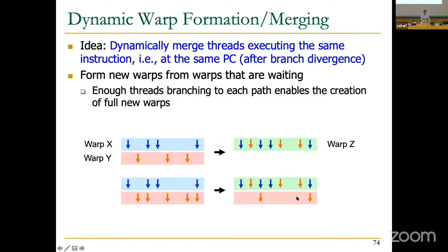Unfortunately, here you cannot eliminate a warp. Why? Because you can see that these two threads in these two different warps have to be in the same lane. Remember, you partition the register file. You cannot move.